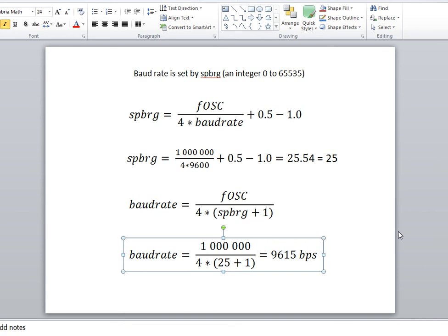USART communication is actually rather flexible. When we say we want 9600, it doesn't have to be 9600 exactly. There's a bit of slop in the protocols for the communication. So as long as you're reasonably close, within a few percent, then you should be able to communicate. Probably you need to be within about 10%.